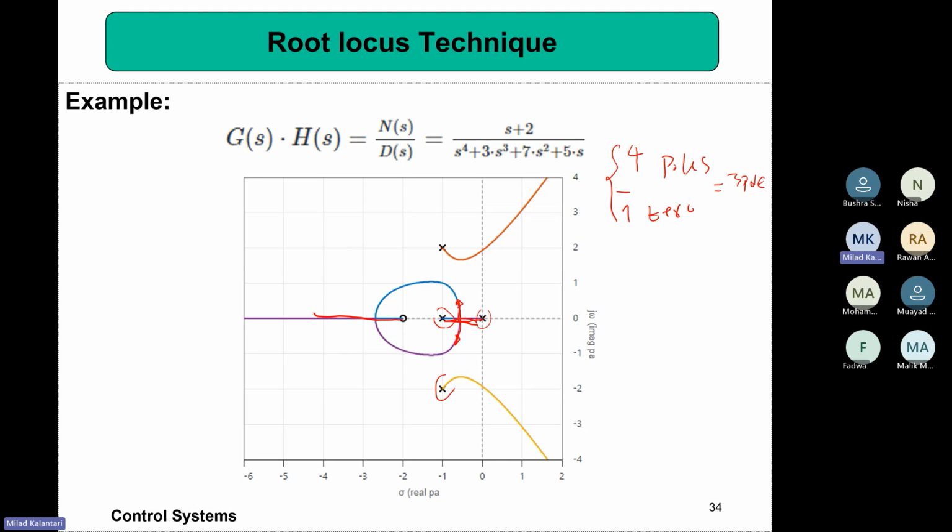And when you are very far, the 3 poles will have 3 asymptotes, from some centroid to somewhere. And then we expect some of the poles should go to the right-hand side, right? From this general knowledge, you can estimate how this can be, even without accurately solving.